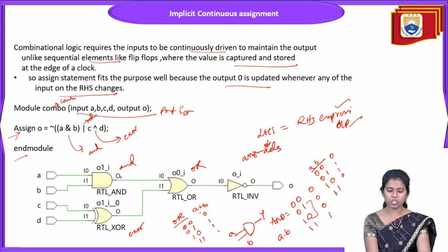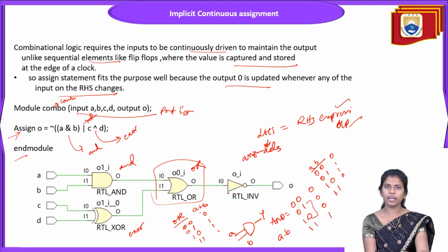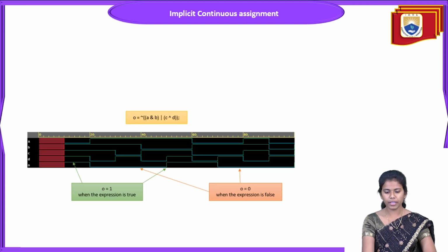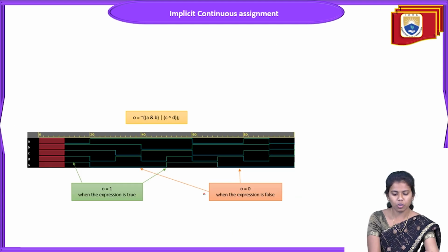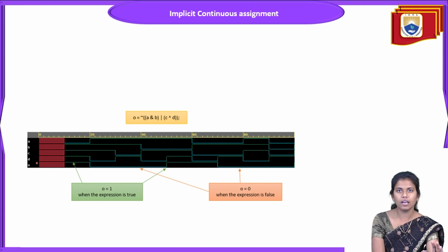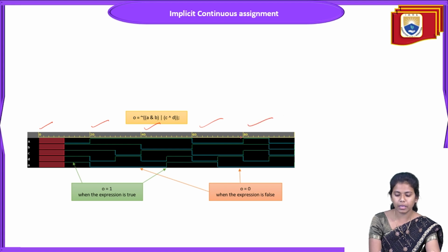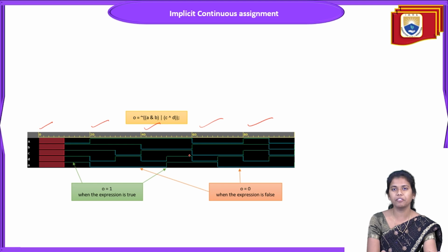My output goes sometimes 0 and sometimes 1. And that 1 I'm giving as an input to the OR gate. And from this OR gate, using the truth table, I'll be getting my outputs. And that output I'm giving to the NOT gate. So here, as per this, we can observe the delay clearly. Here A, B, C, D are the inputs, with time at 0 nanoseconds, 20, 40, 60, 80. This is the timing behavior of the circuit. We can easily identify and observe it.